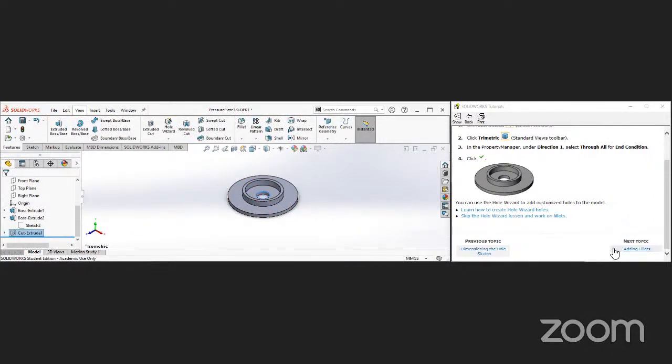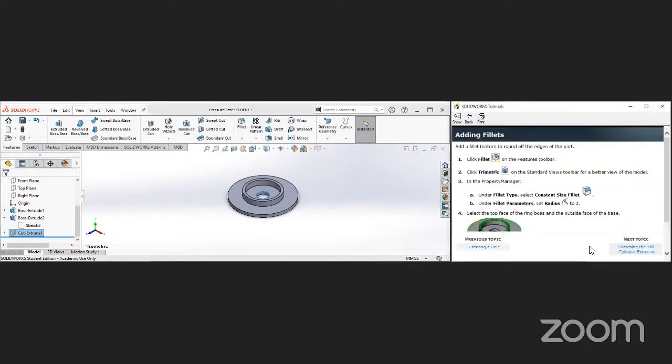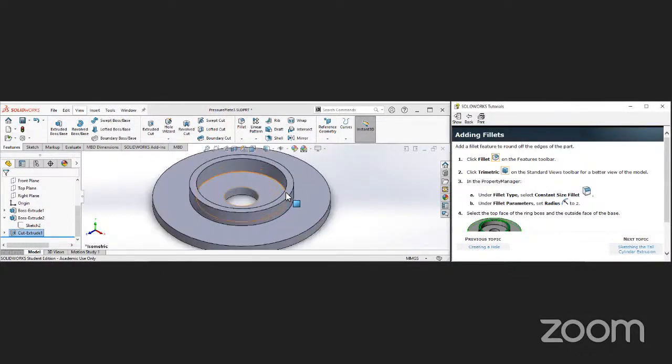That's a nice thing with solid modeling. If you make a mistake, if you click something somewhere else, you can always make up for it afterwards. So let's talk about one of the other features right now, which is a fillet. So all these features right here, they're very, very sharp. If you were to send this off to a machine shop, these can often be razor sharp. And if you're getting the part molded or something like that, often they can't be molded.